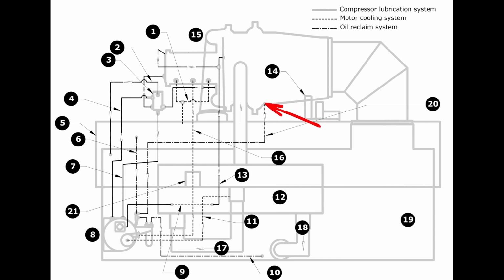So with that, we have this little chamber down here for that oil collection, and we're also siphoning off. Now, all this is suction gas, so we're not drawing in liquid refrigerant here. We're drawing in oil-laden suction gas through this line that will then get siphoned into the eductor and then injected back into our oil tank. And between the two, we're able to get whatever oil may collect in the system that we need to return back into